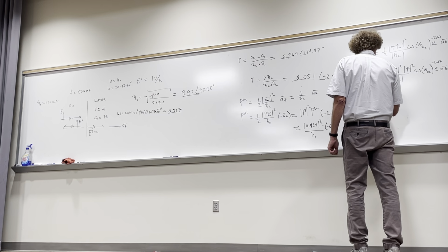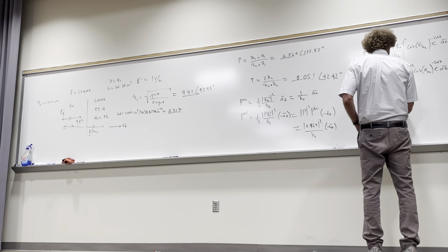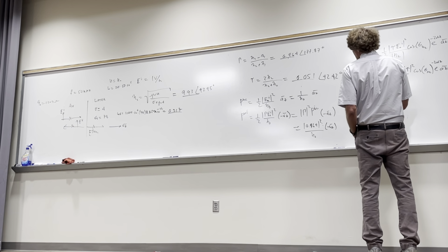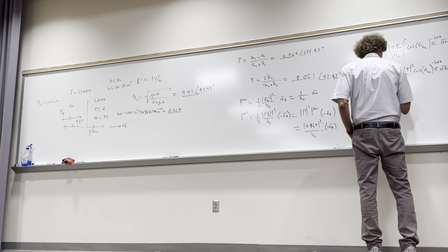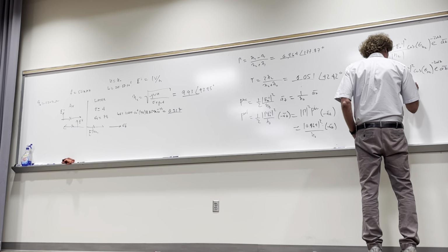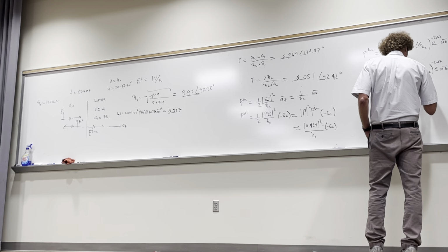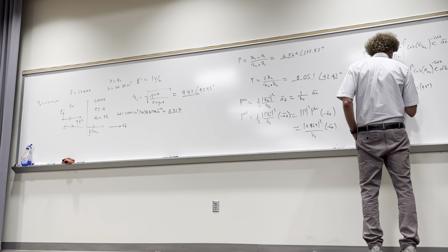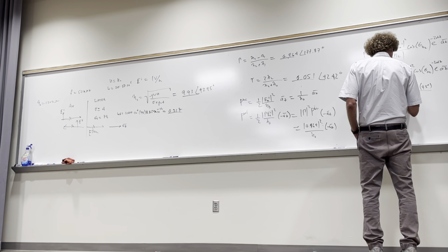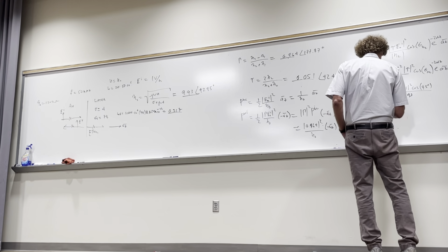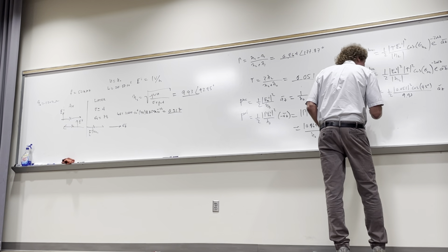This one's going to be a little different. The transmitted power is going to be 1/2. Now the incident field is 1, so I don't have to worry about that, times the transmission coefficient, which is 0.051, squared. And then it's going to be the cosine of 42 degrees, call it 43, over the magnitude of eta 2, which is 9.93. So if you can give me this, I'm going to forget about this part; we know it's going in the a_z direction. I'll forget about the e to the minus 2 alpha z.